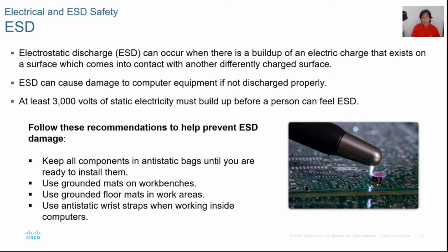Imagine when you have 3,000 volts and you try to hold electronic components, especially components from our desktop PC. You can transfer charge and damage some of the sensitive components inside your computer. So, we need to follow several recommendations to prevent ESD damage. First, keep all components in anti-static bags until you are ready to install them.